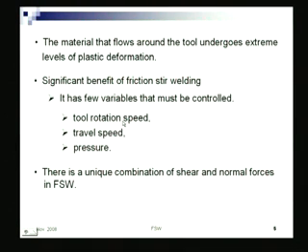Tool rotation speed and obviously the travel speed and the pressure. Pressure is nothing but the downward force, how much you are applying, at what speed you want to move that, and what is the RPM. These are the three primary variables which need to be controlled.